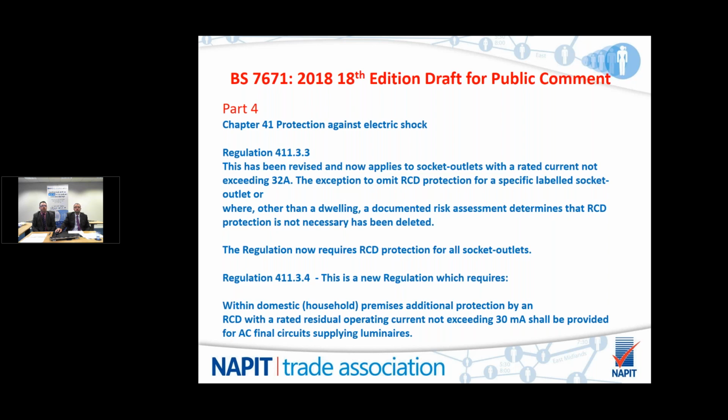But both of those exceptions have now been deleted. So that means within this regulation, all socket outlets must be protected by RCDs not exceeding 30 milliamps. This will lead to every installation having RCD protection for socket outlets.